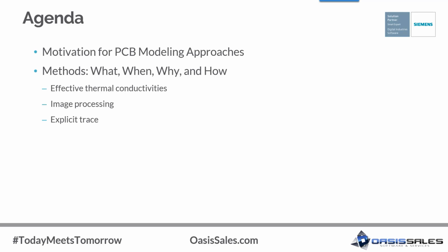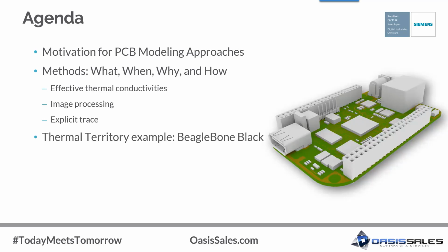I'll provide an overview of the historical method of representing explicit traces and introduce you to two methods of capturing explicit traces in Flotherm XT, one of which is thermal territories. We'll finish with the thermal territory example using the BeagleBone Black board.